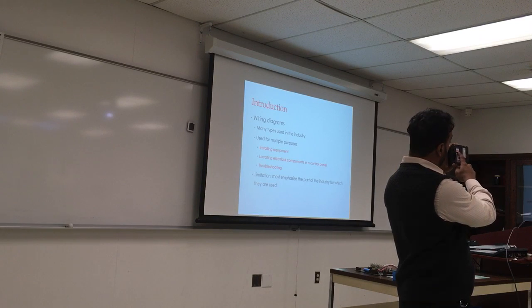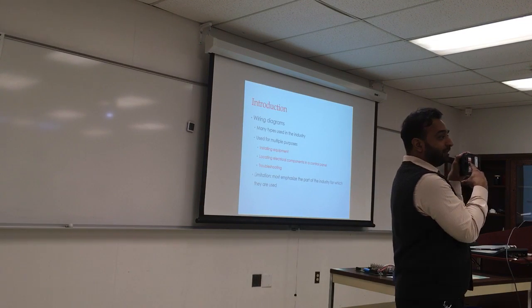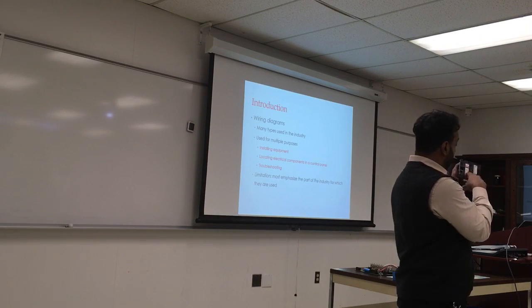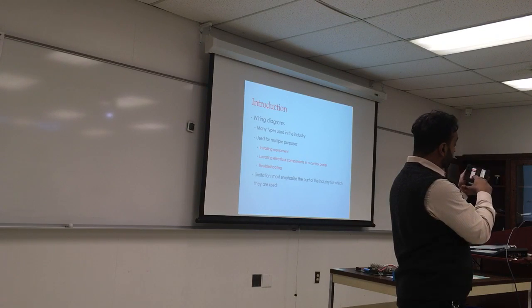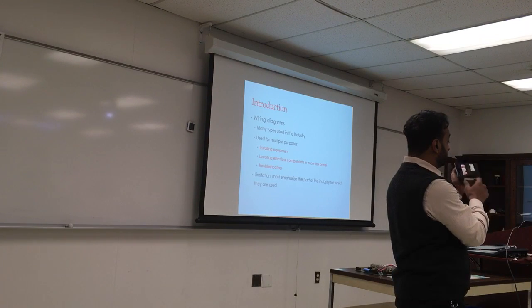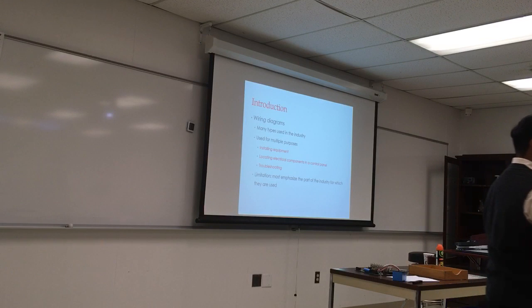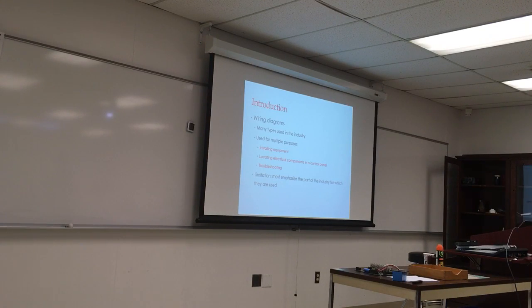So here it says ignition. This one goes to the burner motor. This one is L1 coming in, and these are all neutral. We have something that goes to limit and valve. Don't be overwhelmed now because we will study these very well. And if you look at the top, you will see the small little diagram. If you look at it long enough, probably you understand it's not that bad. It shows the lines and where everything goes and how to come back.